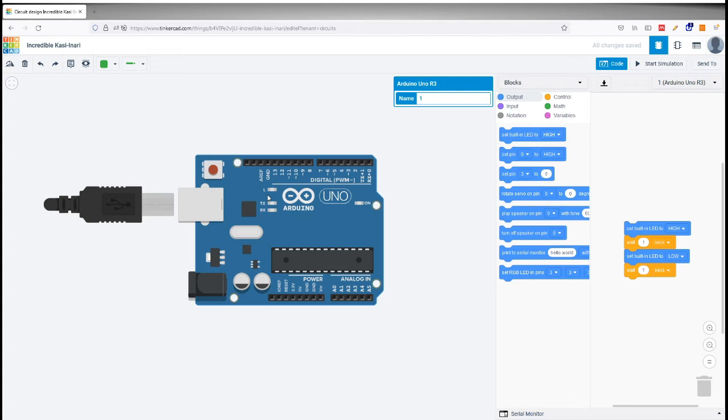But here the problem is that the Arduino microcontroller, it is working on say 12 megahertz crystal oscillator, or say in our case it is 16 megahertz crystal oscillator. That means the time taken for execution of one instruction will be 1 by 16 megahertz, right? 1 by frequency will be the time period. So each instruction will be executed in one cycle or one time period.